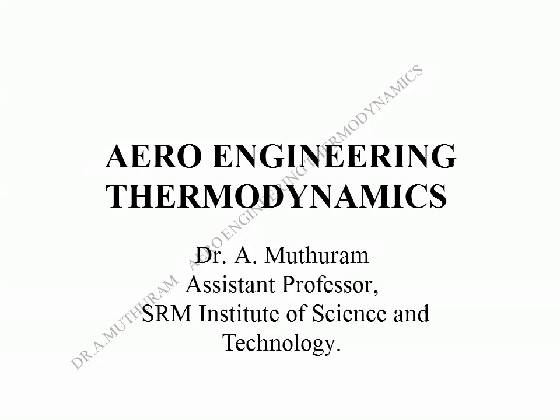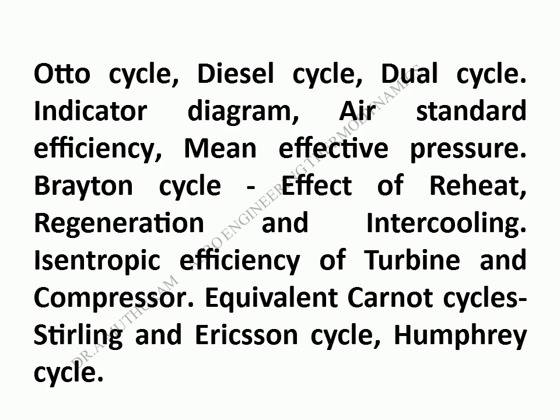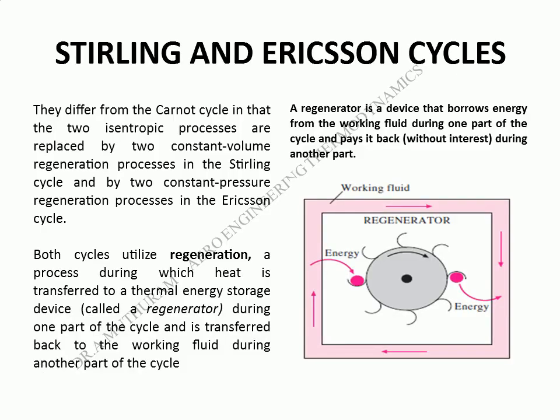Aero Engineering Thermodynamics. Unit 4, Air Standard Cycles. Stirling and Ericsson cycles. They differ from the Carnot cycle in that the two isentropic processes are replaced by two constant volume regeneration processes in the Stirling cycle and by two constant pressure regeneration processes in the Ericsson cycle.